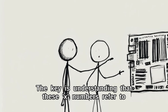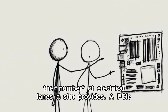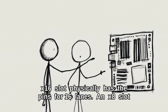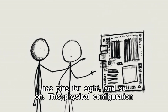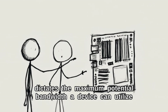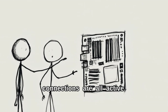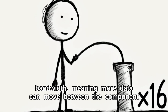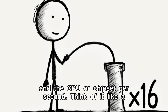The key is understanding that these X numbers refer to the number of electrical lanes a slot provides. A PCIe X16 slot physically has the pins for 16 lanes. An X8 slot has pins for 8, and so on. This physical configuration dictates the maximum potential bandwidth the device can utilize if plugged into that slot, assuming the electrical connections are all active. The more lanes a device can use, the higher the potential bandwidth, meaning more data can move between the component and the CPU or chipset per second.